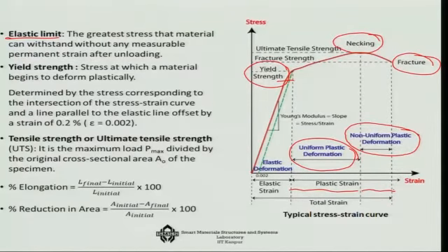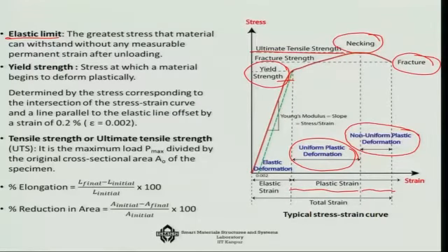And the point that is important for us is that up to the necking, we get the ultimate tensile strength. So, that is the maximum load divided by the original cross sectional area of the system, that gives us the ultimate tensile strength. Beyond that, you would not expect strength of the material, because beyond that, if you take the force, it is going to take us towards a fracture. That is why ultimate tensile strength plays a very important role in terms of the product design.